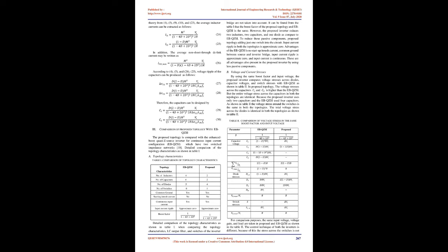Two modulating waveforms, i.e. Vm1 and Vm2, are compared with a high-frequency triangular waveform, i.e. Vtri, to produce pulses. This pulse is used to operate the switches S1, S2, S3, and S4. Compared to another triangle waveform, the dashed line, with a double frequency and half of the amplitude of that of Vtri, a constant voltage is produced for the S0 switch. The S0 control signal is then passed through the OR logic gate to add the shoot-through states in the inverter bridge into the control signals of switches S1 to S4.